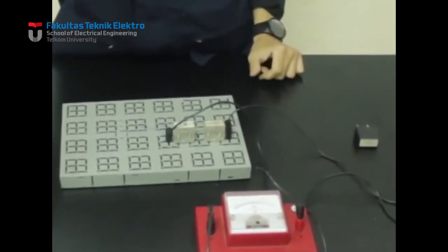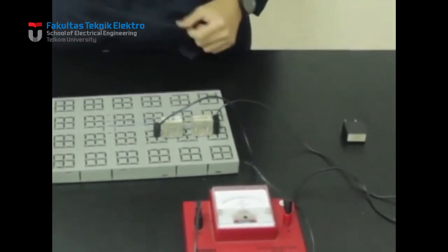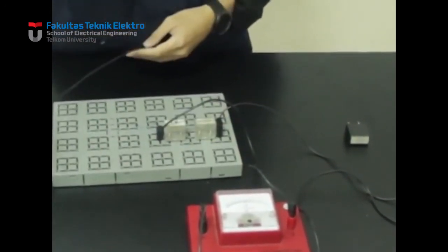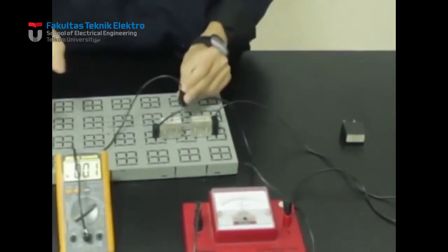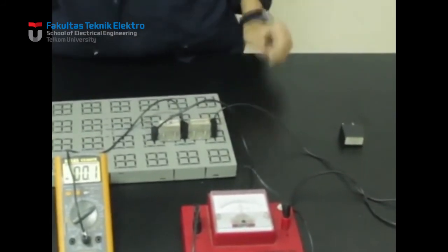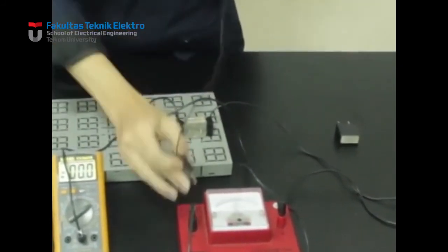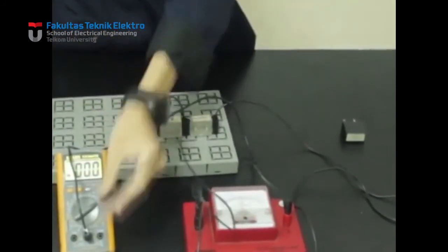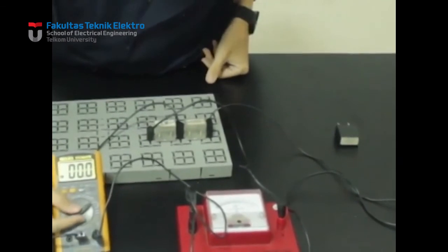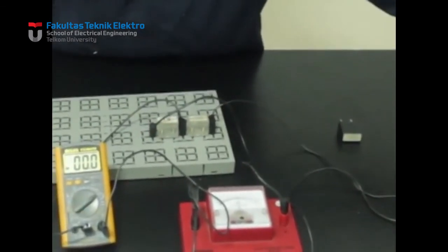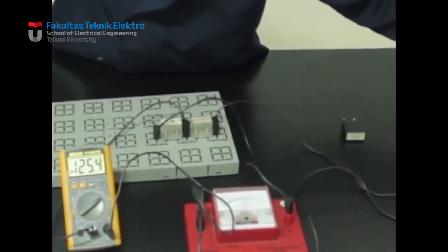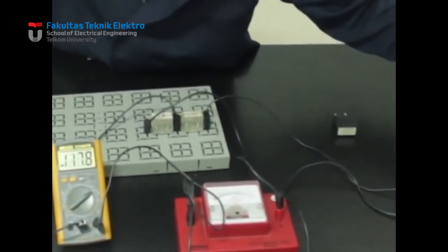In this experiment, the multimeter will calculate the voltage through the multiplier resistor and galvanometer. Therefore, we will parallel the multimeter from before the multiplier resistor to after the galvanometer. This time, the multimeter will measure the voltage, so we will set it to direct current voltmeter mode because it uses a direct current power supply. And now we're going to take measurements.